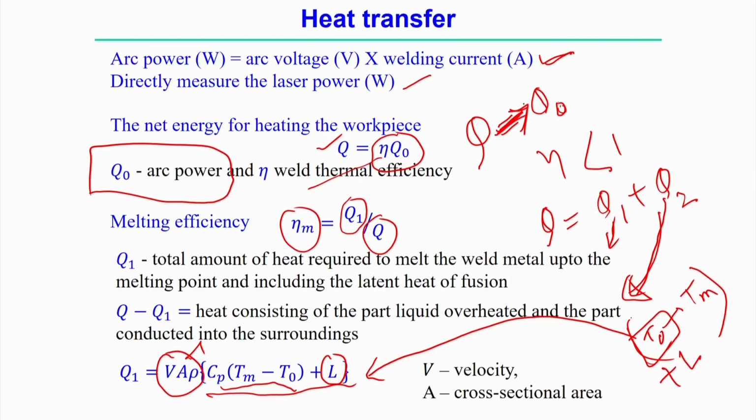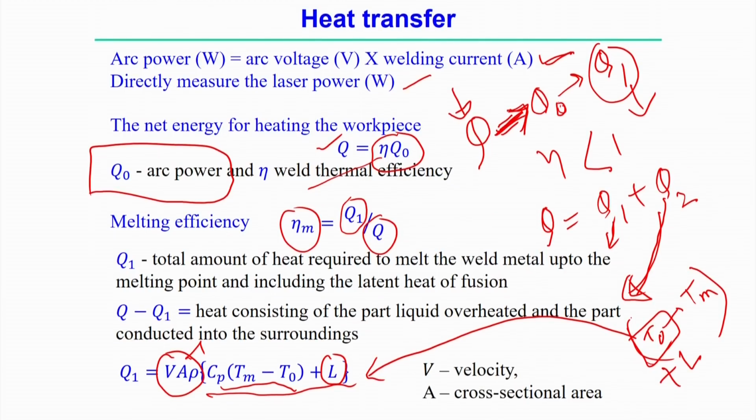So, there is some loss of heat during the transmission of the arc power to the workpiece, then it is Q0, and out of Q0, Q1 is utilized for the melting process. So, the actual supplied energy is Q from the machine itself, and then Q1 is utilized to melt the substrate metal. That means this utilization will definitely be very small compared to Q, and it can be linked between Q, Q0 and Q1 in terms of defining the different efficiency terms.